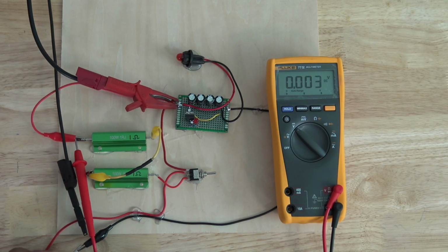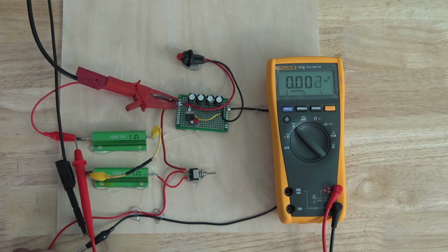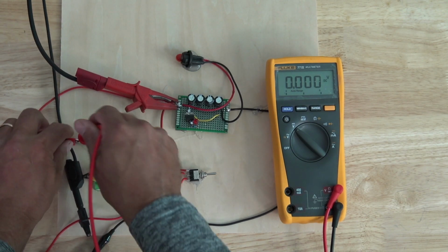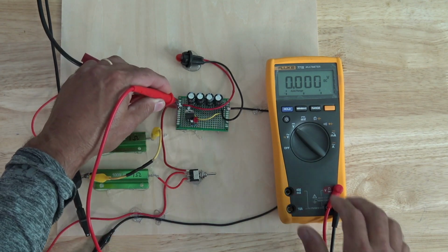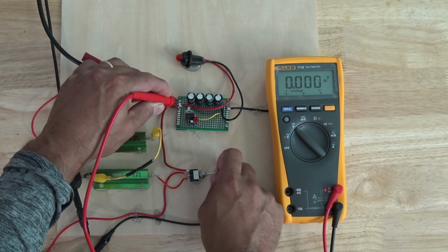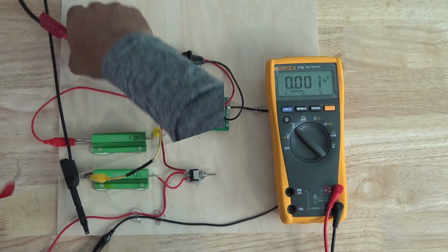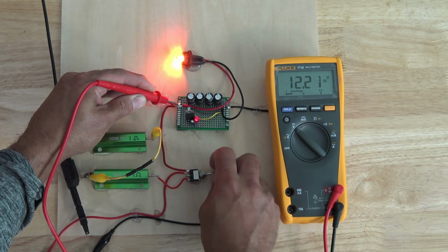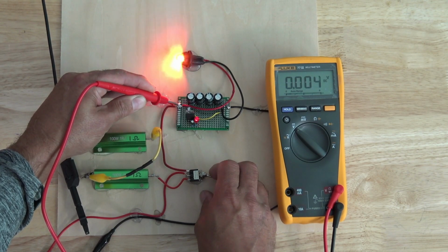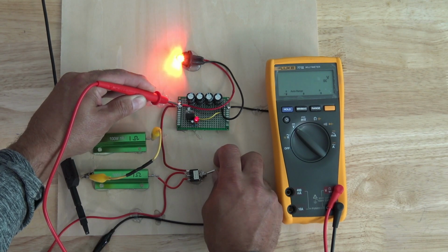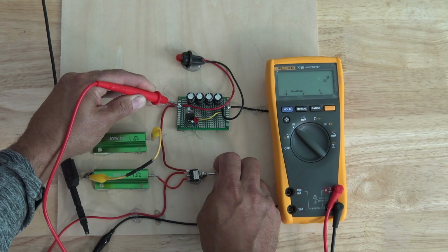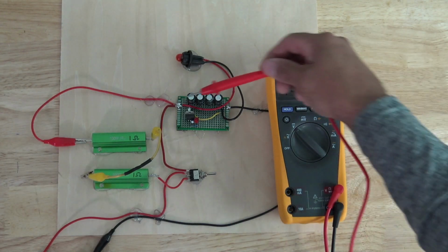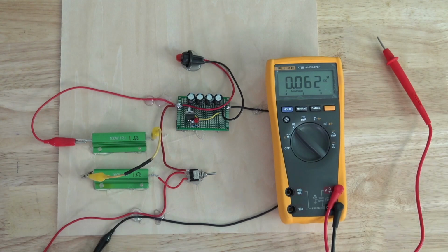I'm going to hook up my multimeter to ground here. Let me just get that. And my other lead, I'm going to hook it right into our power supply here. So when I flip this switch, so taking my multimeter here, when I flip the switch one way, we have 12.2 volts. If I go the other way, I have 12.68 volts. 12.68, 12.2, not a big difference. What does this look like when we're trying to charge up a bunch of capacitors? We have to get the scope out to see this.